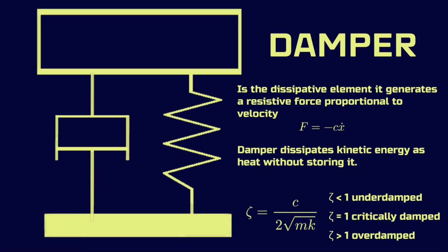A system is said to be overdamped if it has a damping ratio greater than 1, and its oscillation will decay to 0 really quickly. This can be seen in applications such as a hydraulic door closer with slow return or a heavy instrument pointer in viscous fluid.